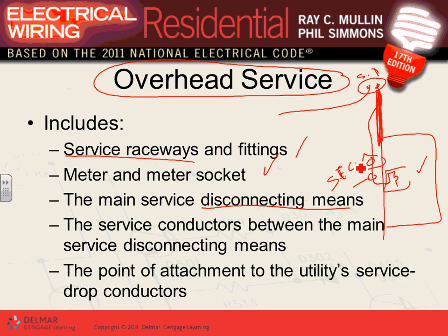Point of attachment to the utility service, to the service drop or that service point, which is right in here. This is my service point where I tie my cables with the cables coming from the electrical utilities. Any comments, any questions? I have a couple of examples, guys. You're going to see the pictures, makes it even easier. But when you talk about service, that's what you're talking about.